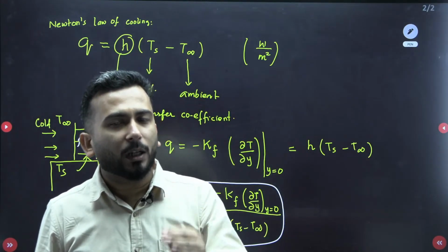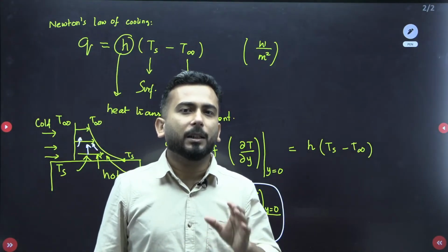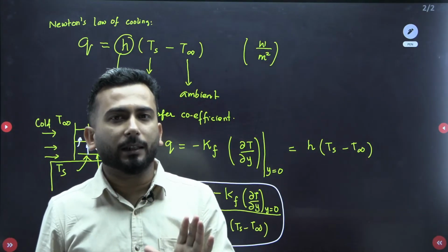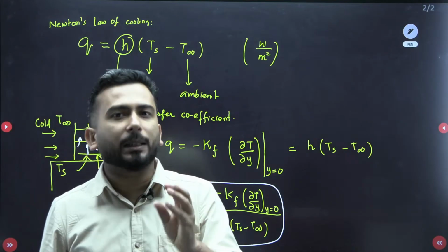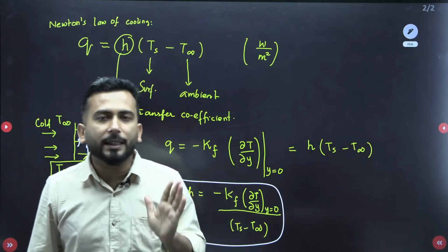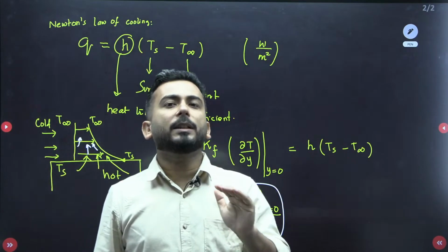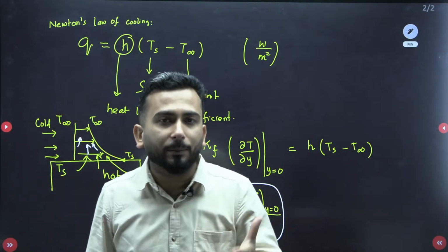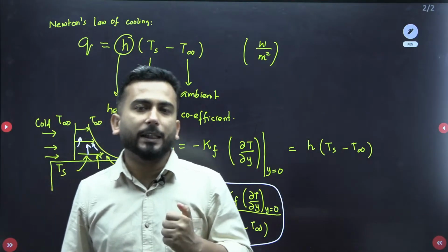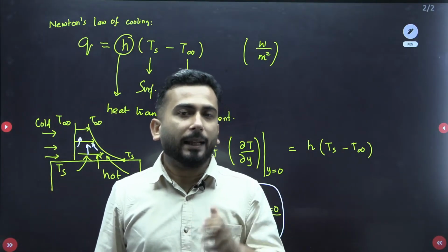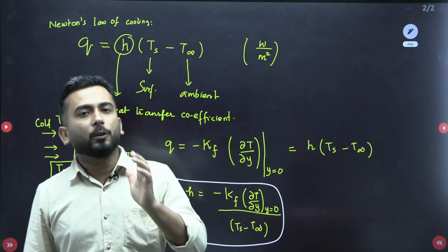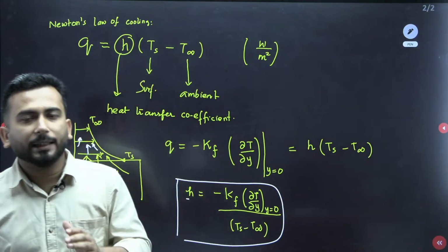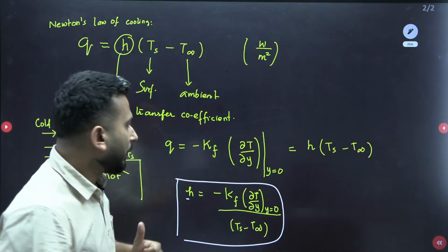But when we talk about convection, we basically mean the bulk motion, and that means there is some enhancement over the conduction. So there must be some quantity which would tell you how much enhancement is there, how many times more the convection is taking place over the conduction, and that thing is given by the Nusselt number. I repeat, that enhancement is explained by the Nusselt number.